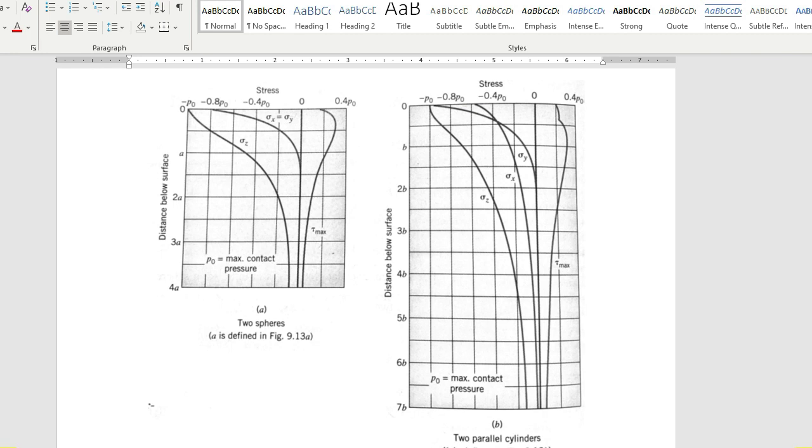And then we look at the depth as a function of half the contact length of the cylinder to cylinder, which is that B parameter that we calculate using the Hertzian values. And so what's kind of interesting here is we have this shear stress profile that actually has non-zero value due to the applied stress initially, and it goes down and actually peaks out over here. Okay, so it's something to watch out for in terms of failure.